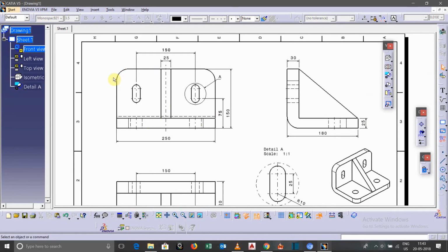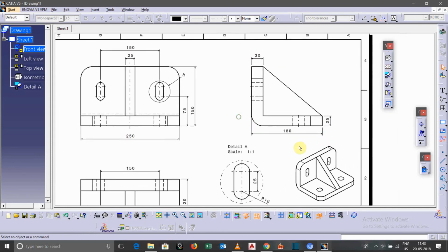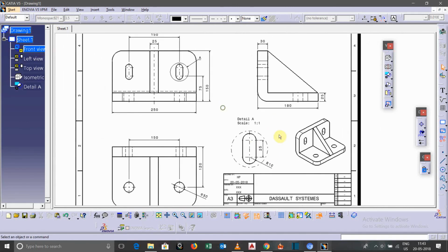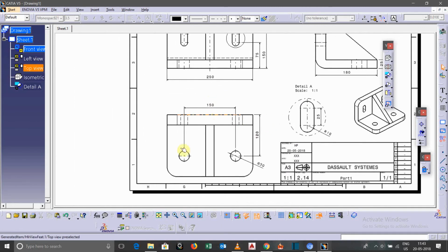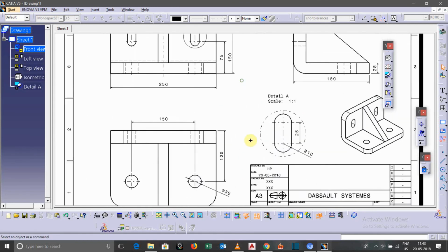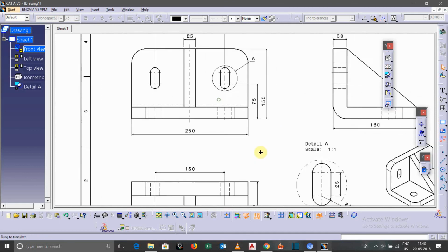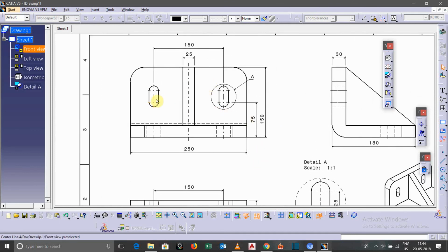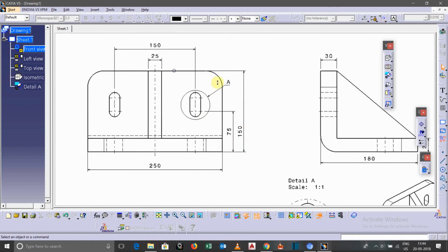So we have this body. For that we have taken this name. We have defined the height value. We have given this pad distance. Now for this body we have taken this 180 dimension. Since we already know the length value from here, we have given height 25. This one is okay. For the hole we have given the distance between two centers and its height from the top end. We have defined the diameter value. So that is also okay. And for this we have also given the center distance between these two elongated holes and the height also.